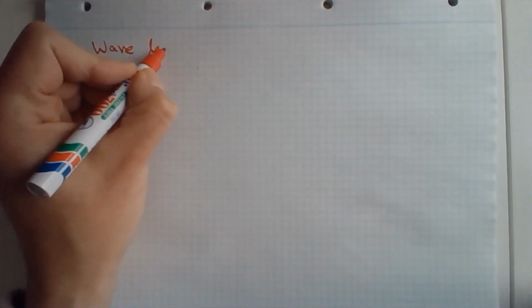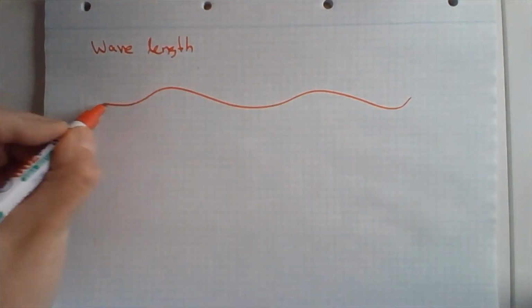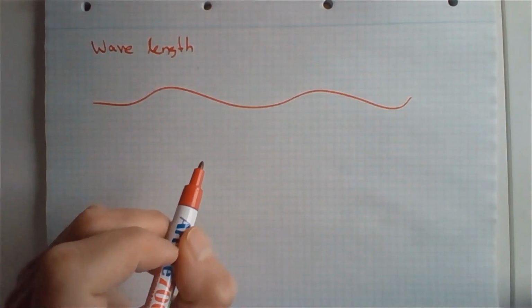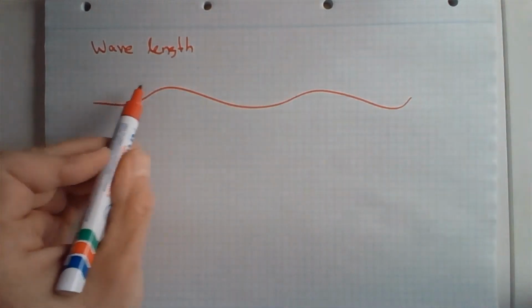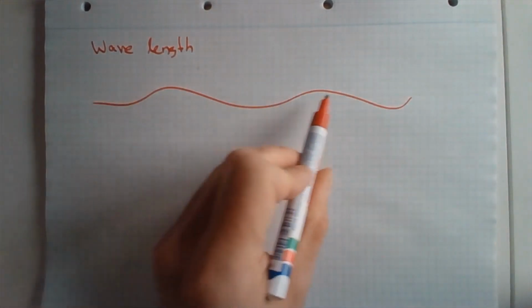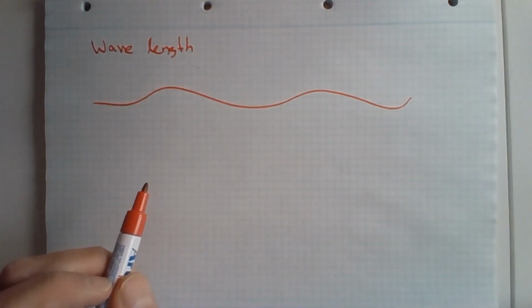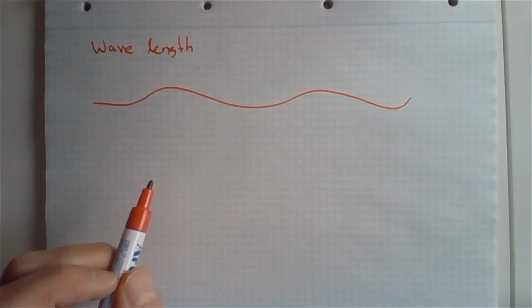Few more expressions that could be useful. Wavelength. Since the pavement itself is not really a time function, but it is a physical distortion of the surface, because we are traveling over the pavement at a constant speed of 80 kilometers per hour, it appears as if the pavement is a sinusoidal input in time, but in reality it's fixed.